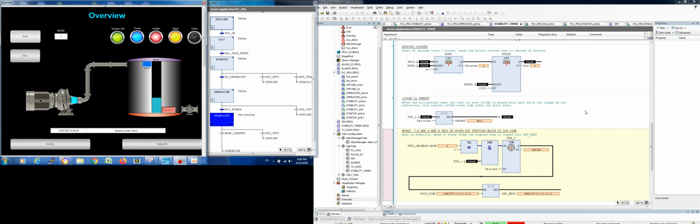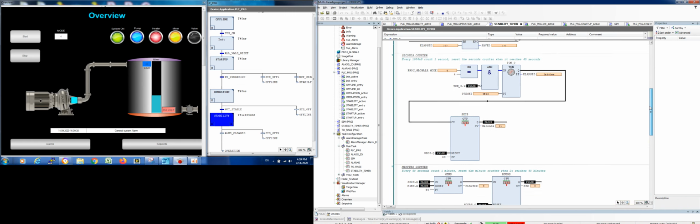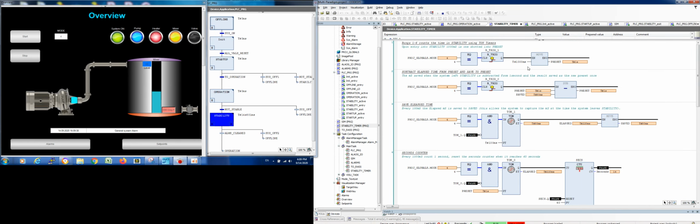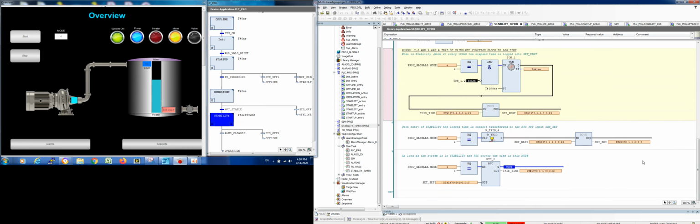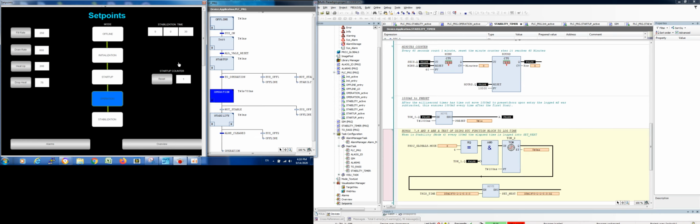Go over here, and in here find that your time, once it goes in this mode, your time has been logged using the timers here. It's also been logged using the RTC function block, and when it comes out, it logs the time that it's spent in there. Found that the RTC is a bit more accurate than trying to count time with a timer.